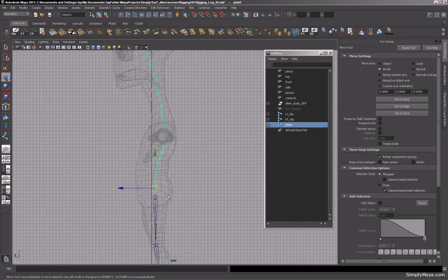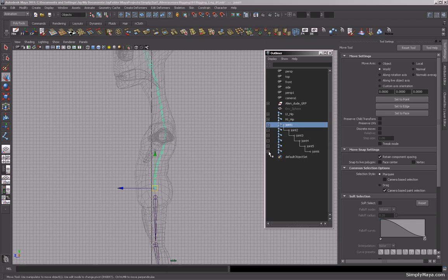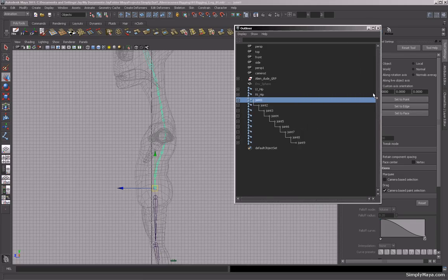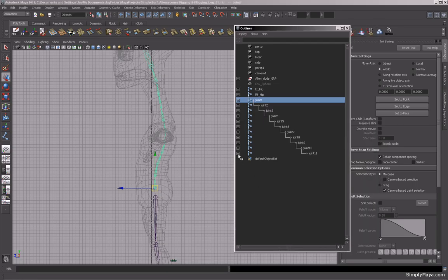So what we're going to do is name the first joint. Let's just open everything out. So we've got quite a few going on here now. So we'll just open this set out. Okay, and there we go, 12 joints. Okay, so joint 1 will always be called the root. This is where everything on the character is going to be connected up, including the legs, and this will enable us to get some nice movement once we get the legs and IK handles, and everything should hopefully begin to follow. So I'm going to type root for that, and then joint 1, we're going to call that back 1,